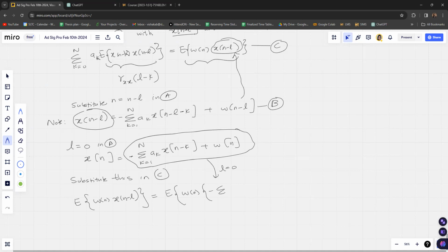So in that case, this is the white noise, right? As you know, white noise is a very random signal, and that randomness cannot be compared with another signal. So if we take the X signal, xn, it is completely independent of wn. Xn and wn are independent. And therefore, once we take the expectation of the product of these two components, it will be 0.